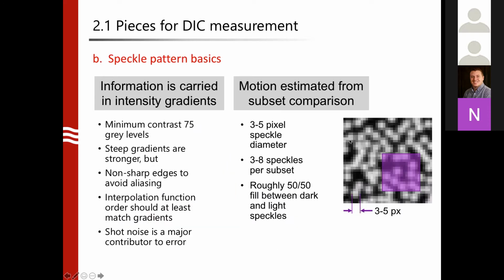So this is what a typical pattern looks like. Basically, you want the entire top surface of the sample to have random, very nice black and white dots, or they may not be dots, but some parts white and some parts black, and they are random. And each typical feature or dot, for example Q1, should have a size of about 3 to 5 pixels.